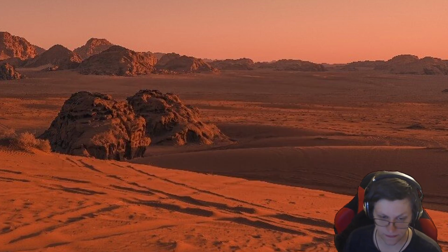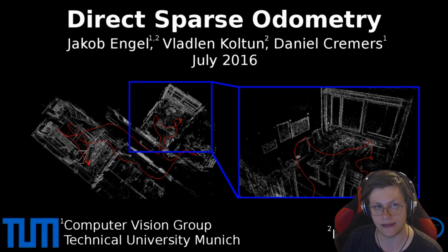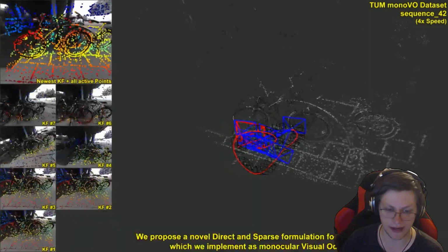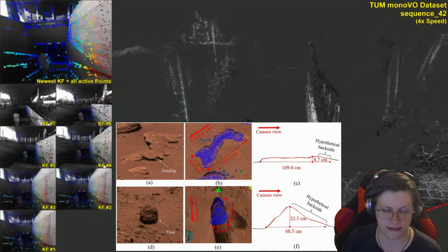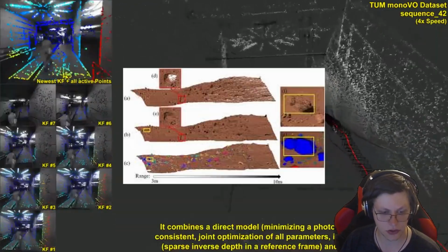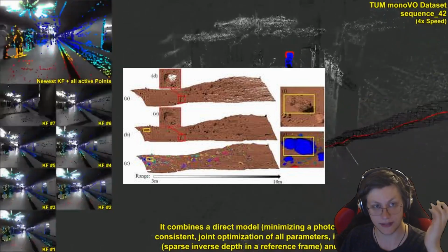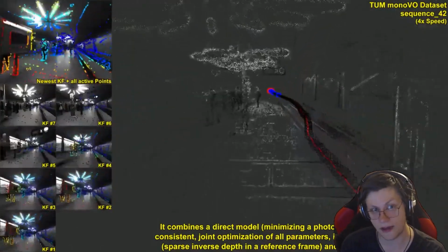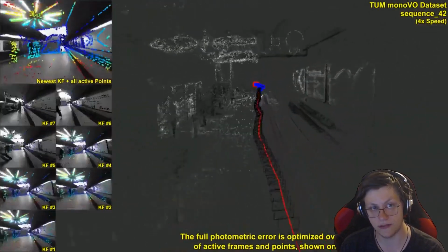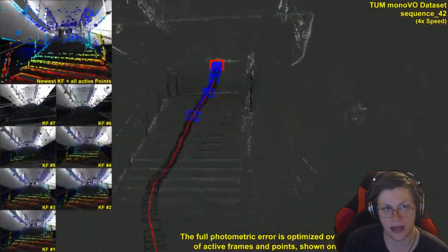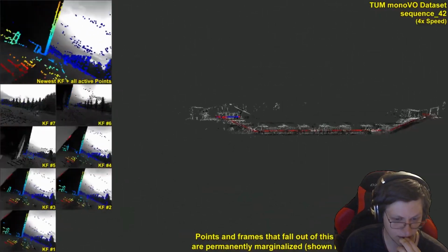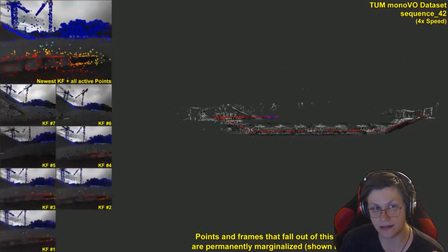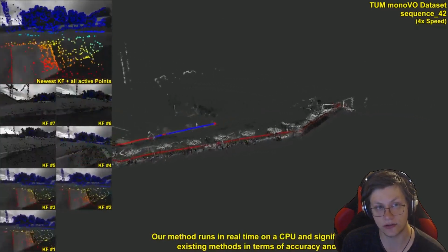And moving one step further, we can use this data we collected with odometry to build point clouds. So we can map our surroundings, where is a stone, where is a cliff, stuff like that, and save it as a 3D mesh. This has some big upsides. For example, if we ever go back into this territory, we already know where we can and can't go and can route our way through the area way more efficiently. It's also interesting for possible later landings to see where is a good surface where we can land.